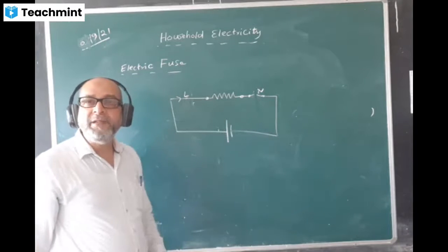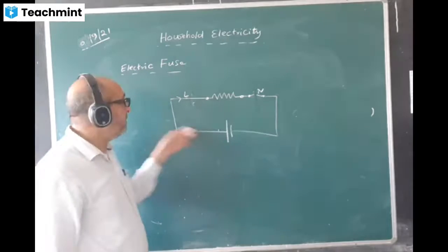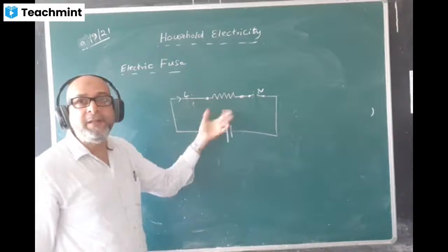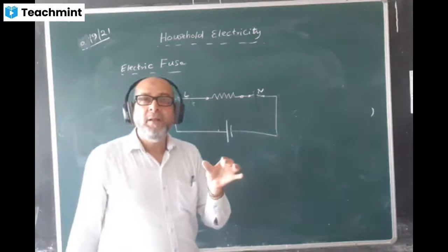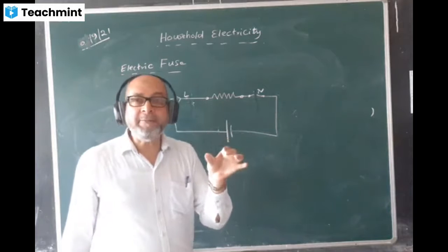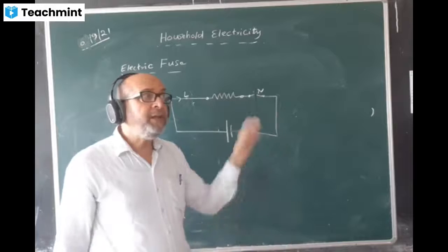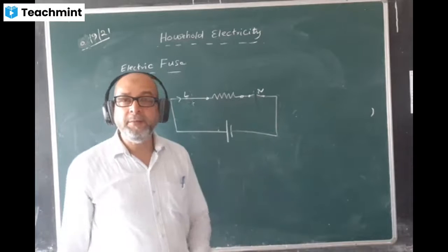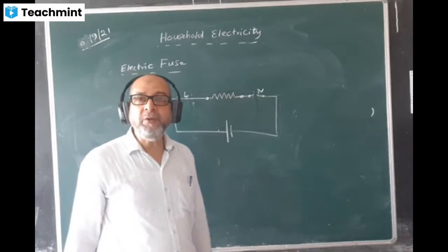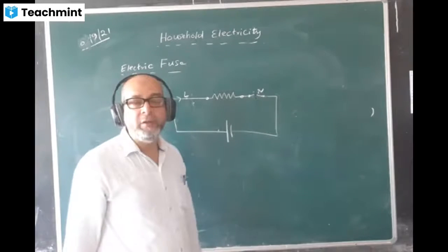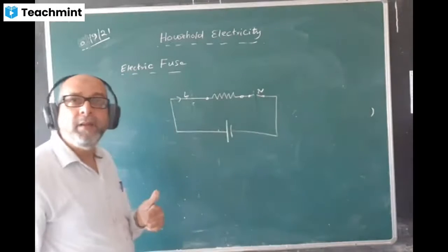Damage cannot be prevented. The appliance will get damaged. Due to flow, this current is coming, still it is coming, and the appliance is already receiving current. We don't want high current to be received by the appliance. This is the reason why we are using a fuse. We are protecting the appliance and preventing its damage. That we cannot do if you connect the fuse in the neutral. Understood or not? Tell me.